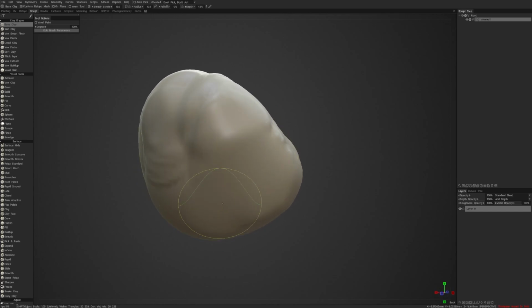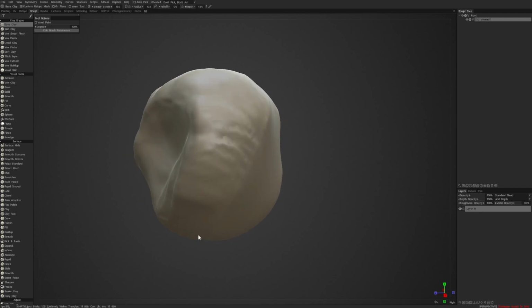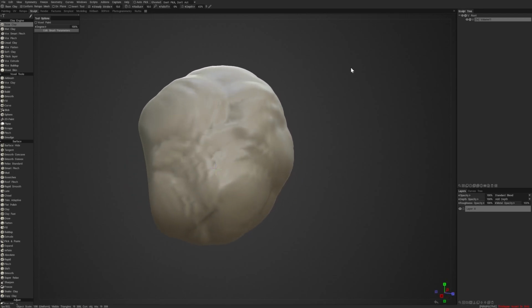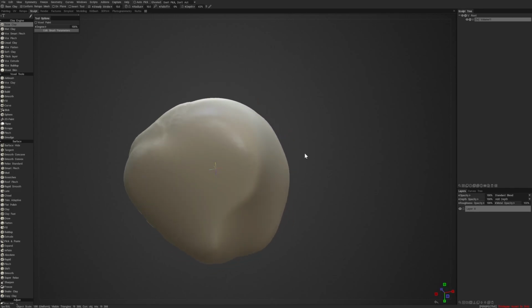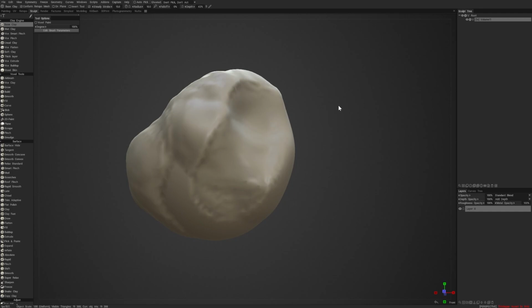All right, so I can hold down the shift key to smooth things out. And you'll see what I'm doing. I'm left mouse dragging off my sculpt to tumble it around, to tilt around. I can pan. I'm using a stylus. Touching down with my stylus on the screen is the equivalent of a left mouse click.